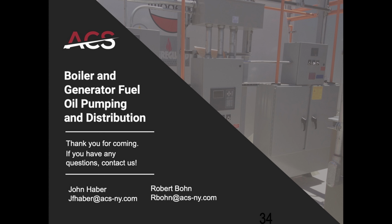If you look at the New York City Code 1305.7.4, you're going to notice there are requirements for the head pressure for those tanks. So the New York City approved alternate design is, again, rated for 25 psi. It can handle that back pressure in the event that the vent on your day tank goes over 5 psi. So a UL 142 tank, if your vent line is higher than 12 feet, you've surpassed the pressure rating on the UL tank, and you won't be able to use it.